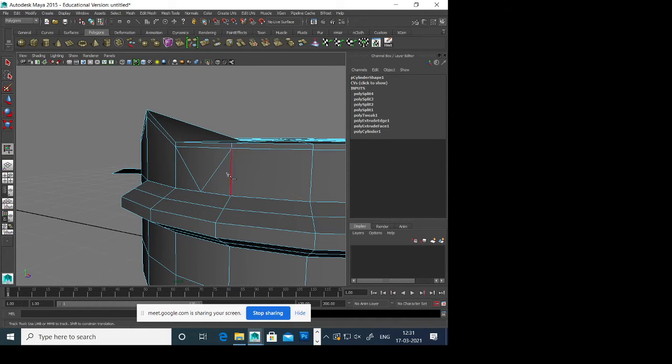So both the tools are combined, so it becomes really handy to create any model, because every time you go to that slice tool or connect tool and connect it, or then cut it, it takes a lot of time. Also, cut sometimes doesn't snap perfectly, and you have to manually weld it again. So in this case, suppose I want to create something, click and drag.